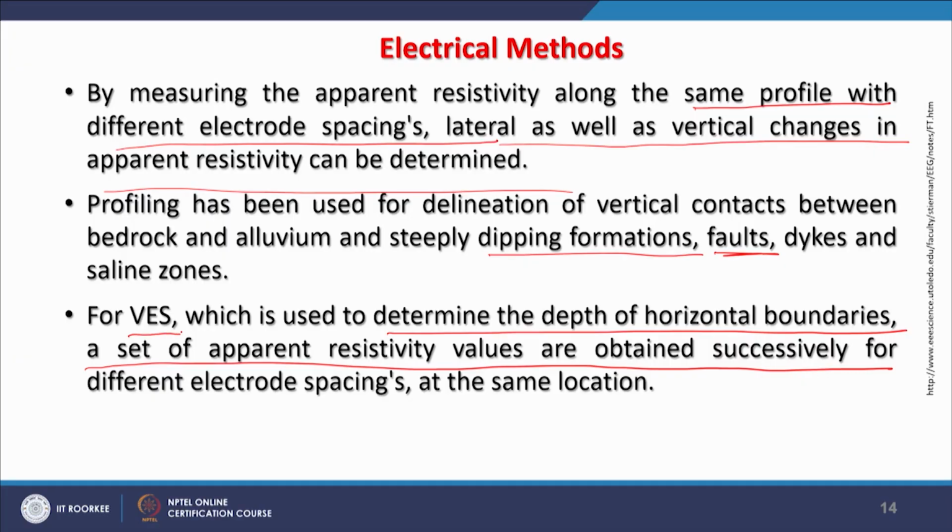If some areas have a real big problem of groundwater, then I would suggest VES is much better. It will give you the complete idea about subsurface conditions, about aquifer, saturated zone, water table, fractured and weathered zone; all kinds of information can be obtained.